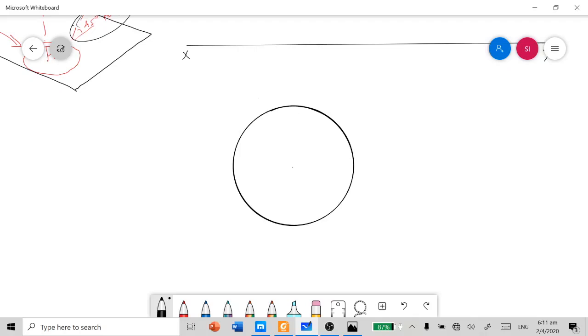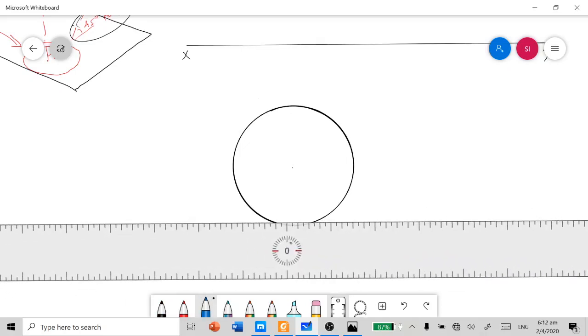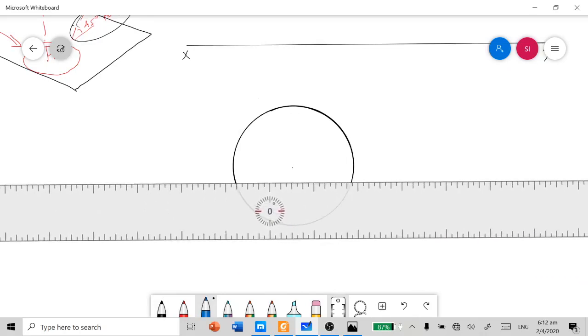I already told there are no corners to be named in this circular base, but for our drawing purpose we can mark the generator points in this circular base. First we need to split this into 8 equal parts.